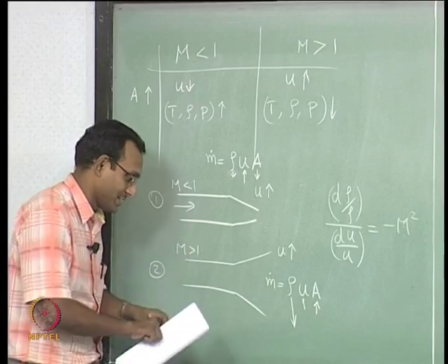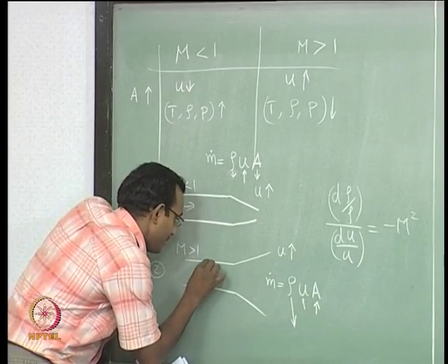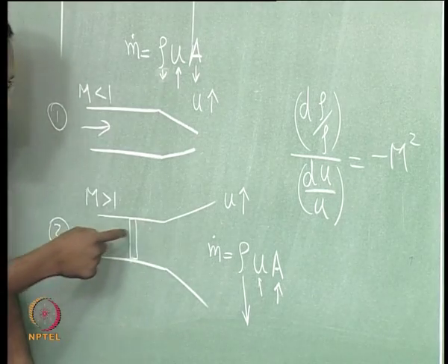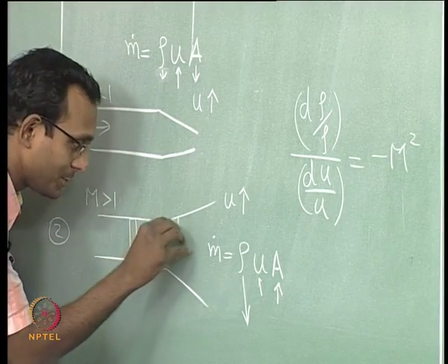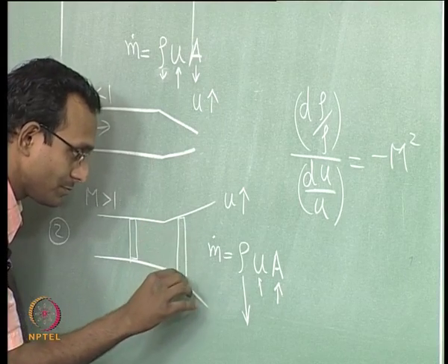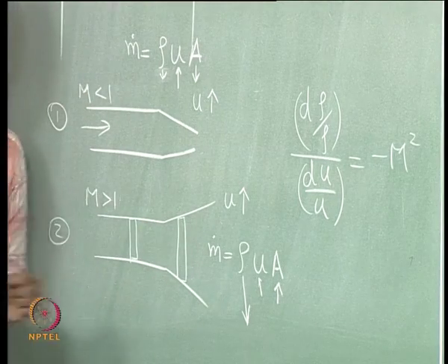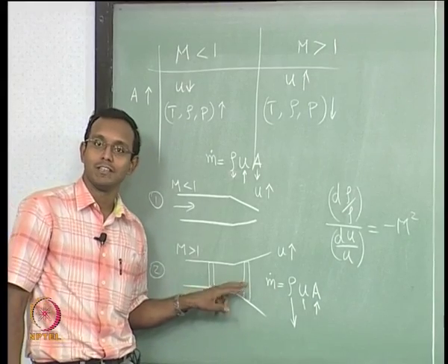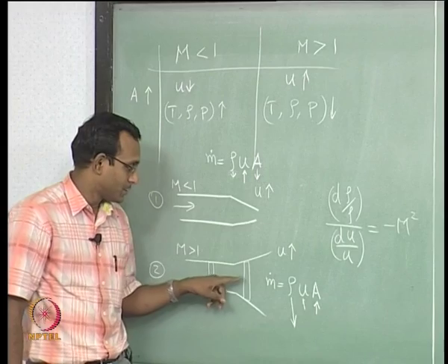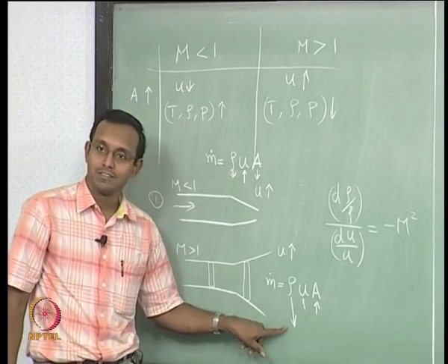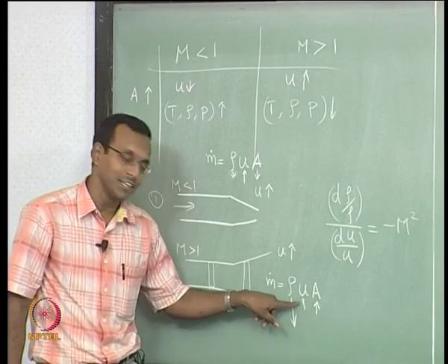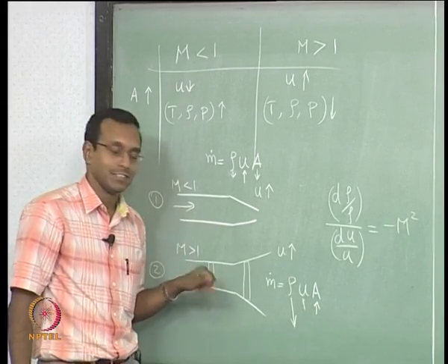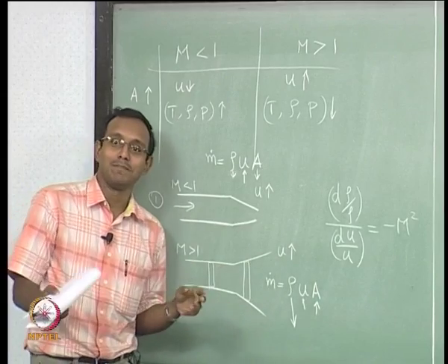I am trying to say that there is some particular fluid element, say a disk of fluid coming through this tube, that disk suddenly wants to occupy this whole region, it will just suddenly expand and occupy this region, because that is the fastest thing it can do, it will just expand. It so happens that it expanded too much that it has to increase velocity for it to satisfy the remaining mass flow rate. That is what is the physical feel I am trying to give you here.